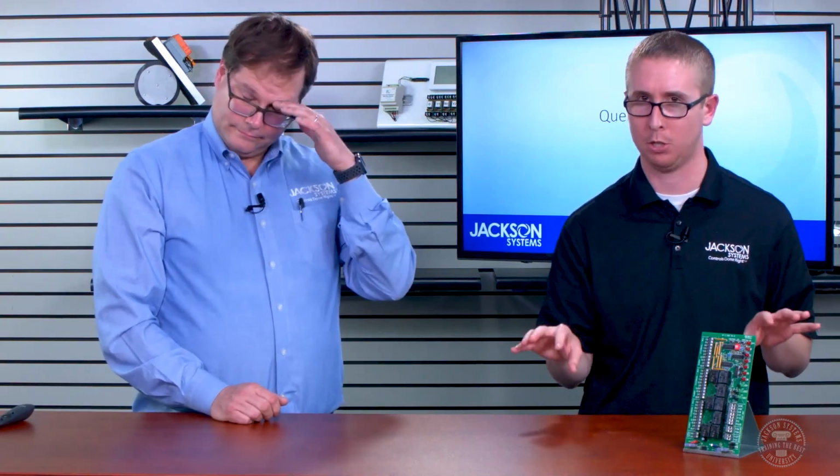And it's looking at what the duct temperature is, whether the air is hot or cold. Usually, I believe both of these two products, whether it's two-position or modulating, are going to determine 72 degrees as kind of the give point. So if it's below 72, it's saying that's cold air, and if it's above 72, that's hot air. Based on those two pieces of information, what it sees is the duct temperature reading and what it sees the thermostat calling for, it's going to open or close that zone damper that it's connected to.